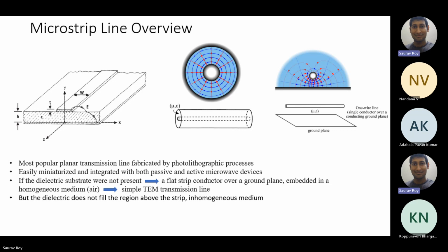Because the inner conductor carries the signal, let's say plus V or minus V, and the outer is shorted, so the electric field lines are radially outward. But this is not always outward, because the signal is sinusoidal, so it will sometimes be outward and sometimes inward, changing with time. But at a certain point of time, you can take it like that.